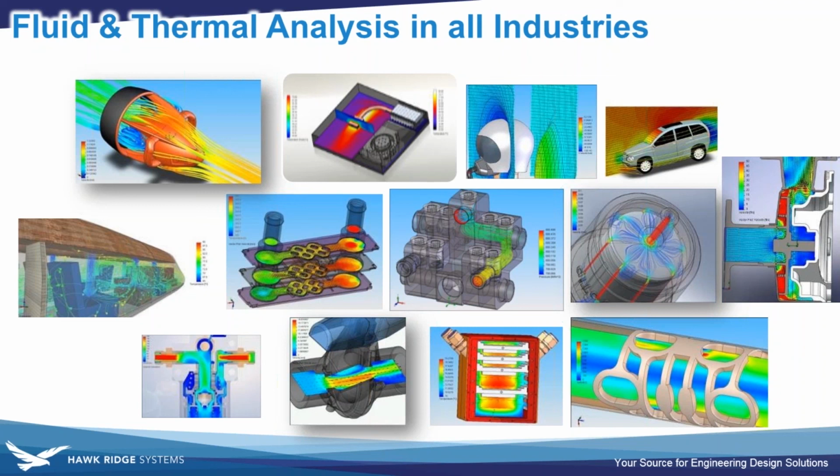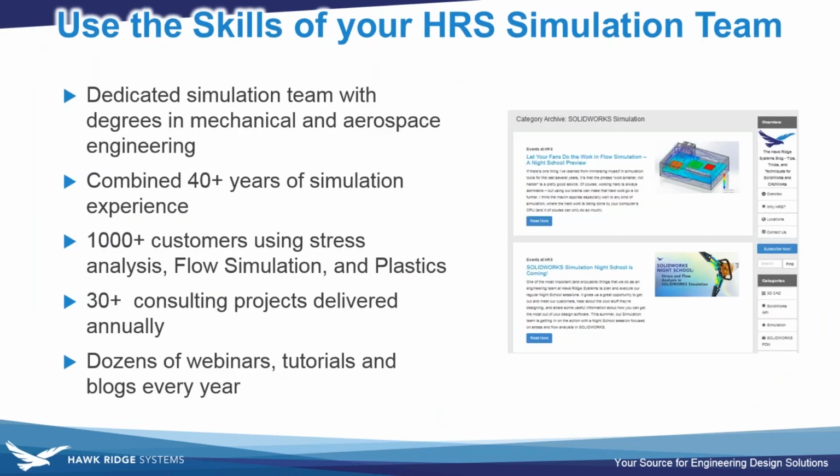And just to give you an example, some of the services jobs that we've done in this realm are things like simple SOLIDWORKS Simulation static analysis. We did a situation where there was a basic thermal stress problem, and the customer was concerned about fatigue of that stress. So that involved doing a thermal analysis to estimate the temperatures in basically a conducting piece of copper, figuring out not only how hot it got, but how much stress there would be from that thermal expansion, and then doing fatigue analysis to predict the life.